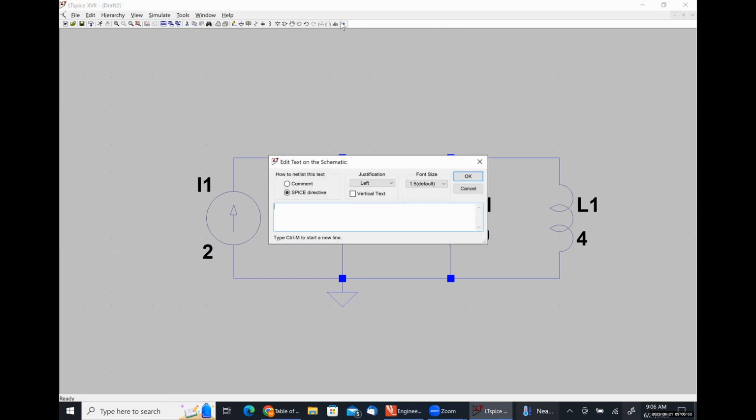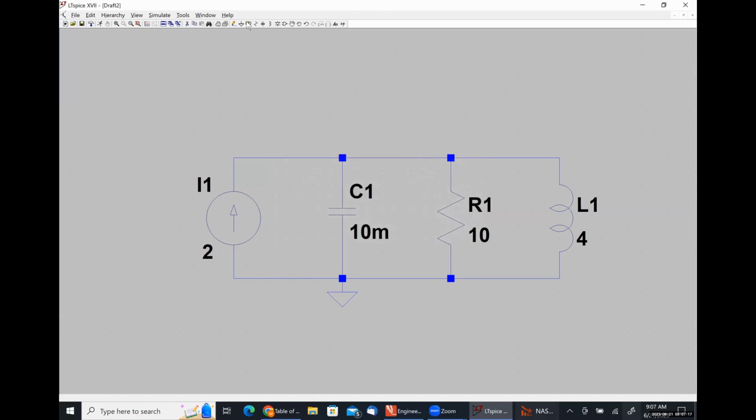So effectively, I'm telling the circuit what was going on at t equals 0 minus instead of simulating it. And then I'm simulating the circuit for t equals 0 plus and beyond. So I'm going to put in my initial conditions by doing .ic. Actually, let me fix this. So this is how I usually do it. I label the positive polarity terminal of my capacitor as VC, and then I put in that SPICE command.